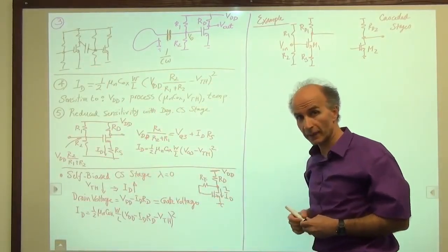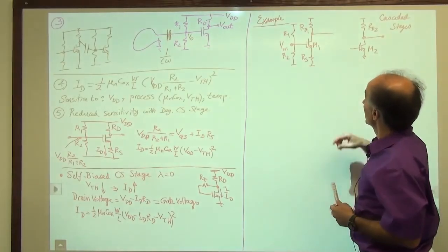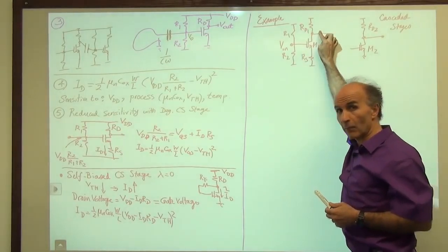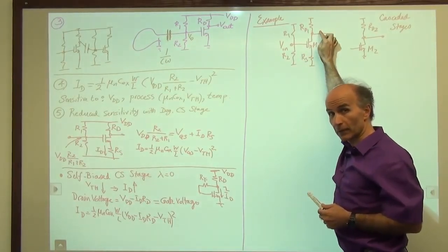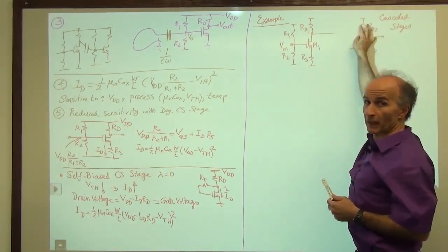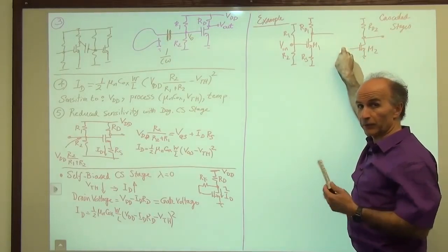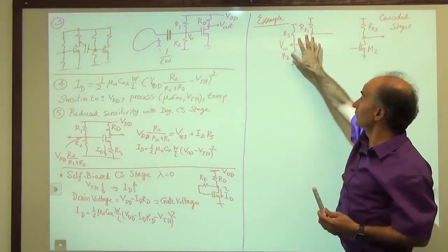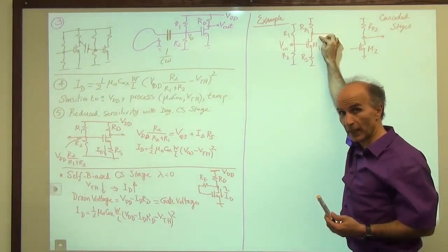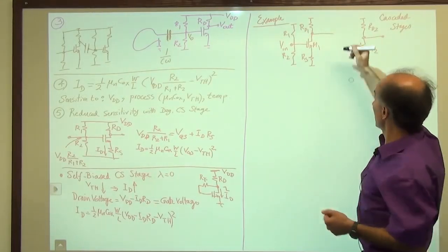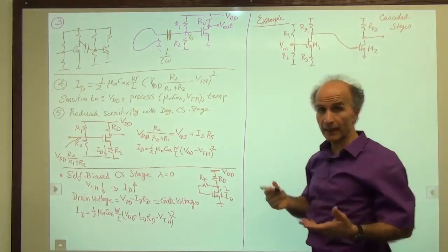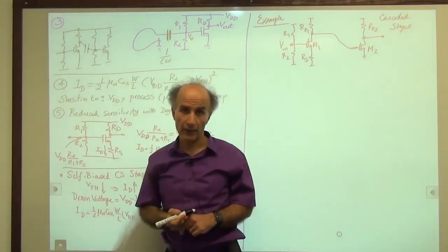And to avoid using that capacitor, what we try to do is we design this circuit so that its drain bias voltage is agreeable with what the gate voltage of this should be. So let's say we design the stage and we said the gate voltage should be 0.8 volts. Then we go ahead and design this circuit such that the bias voltage at the drain is also 0.8 volts. And now we just connect them directly because the two biases agree. So then we connect them together, and these two are biased at the same time together. So we can do that.